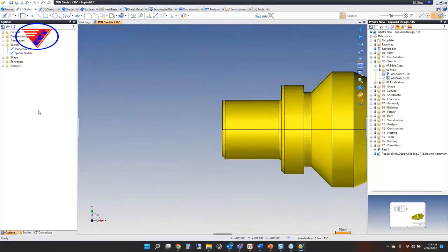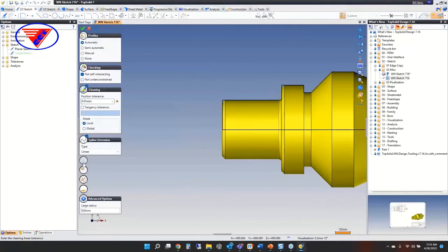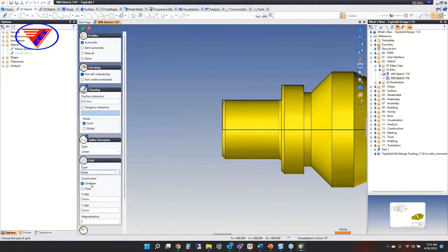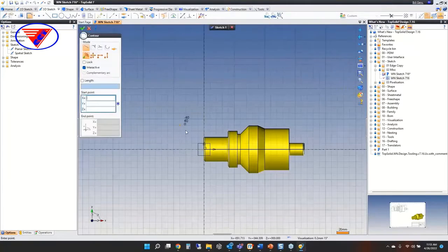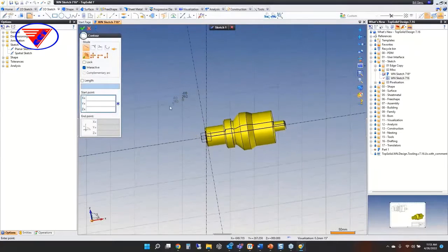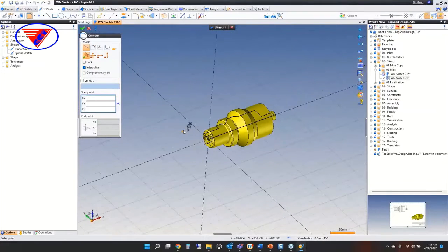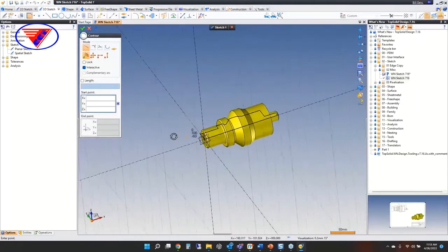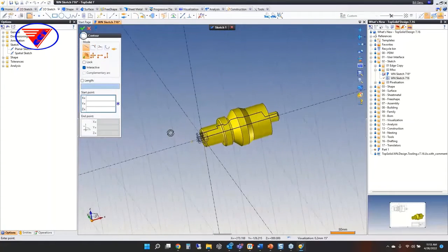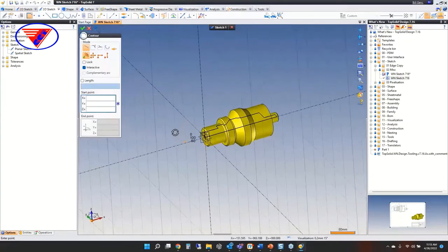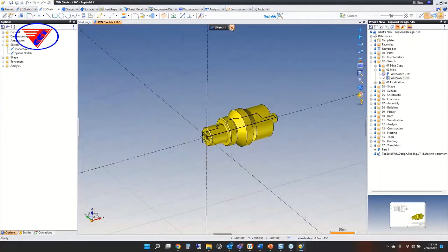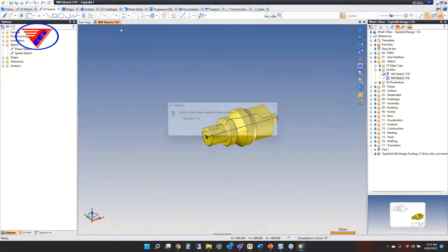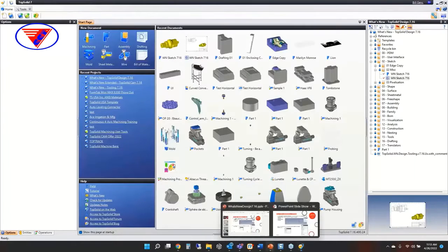You even have the ability to have that turned on in a spatial sketch. So for example, I can go here and say, you know what? I want lines in my spatial sketch. And if we go here to 3D and we start a sketch, okay, right now, yes, we are on my XY plane, but maybe I want to switch to my XZ plane or my YZ plane. So it just helps with visualizing where you're at in that 3D environment, okay? So again, nice, useful improvement. Let's go back to our presentation.